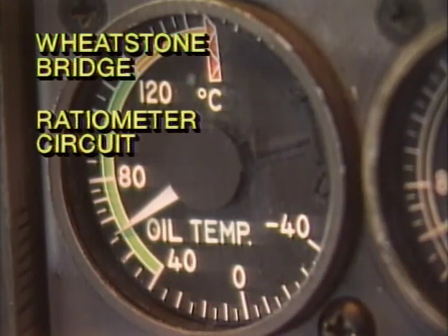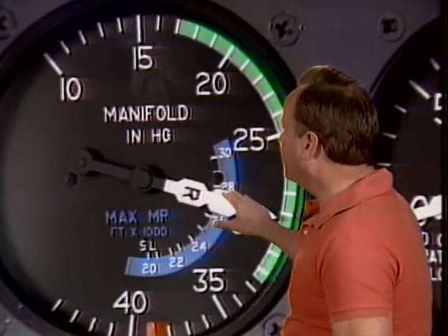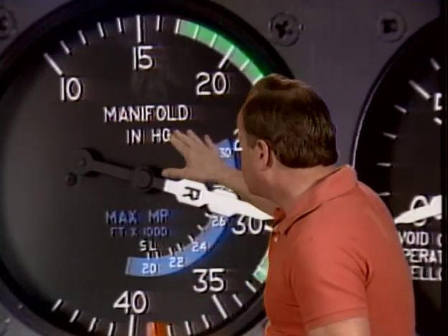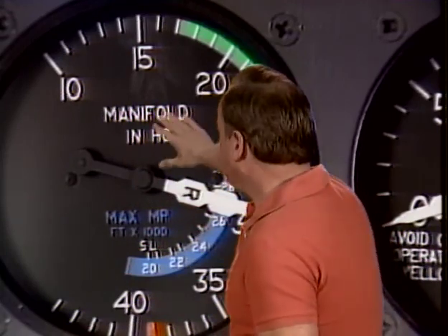Of course, another kind of gauge they're going to ask you about is a manifold pressure gauge. They're going to say, all right, what does a manifold pressure gauge measure? And the answer is it actually measures the absolute air pressure in the intake manifold. Whatever the air pressure is at that time, it absolutely measures that. Now, let's assume you have a break in the line between the gauge and the intake manifold of the engine. What's going to happen? Well, they want you to know the gauge will measure atmospheric or ambient pressure, just outside air pressure. It might be 28 or 29 inches of pressure, but it's going to measure ambient pressure if you have a break in the line, because it tells you whatever the pressure is, and if you have ambient air getting in there, it's going to measure that. That's what it tells you.